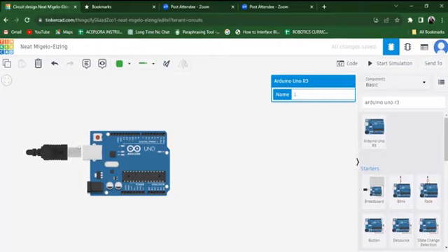You can see it on the screen is already connected. It's showing you that something is connected there. Now, if you see this sign here, it tells you that that's a USB. So that is basically the point where you also send in your code, but you can also power your board from there. When you plug it into a USB terminal, possibly your laptop, you get your board powered. Another point is called the AC adapter in, the AC adapter power in. When you have an AC adapter, this one you plug to your socket. It has a rectifier that converts it to DC, and it uses that in powering the board.